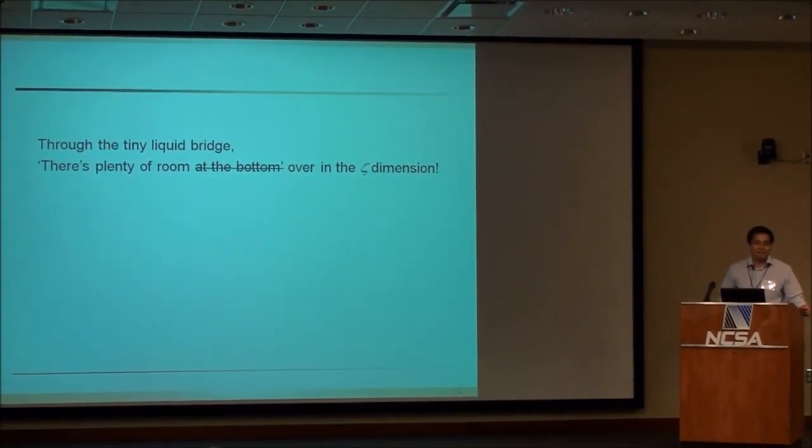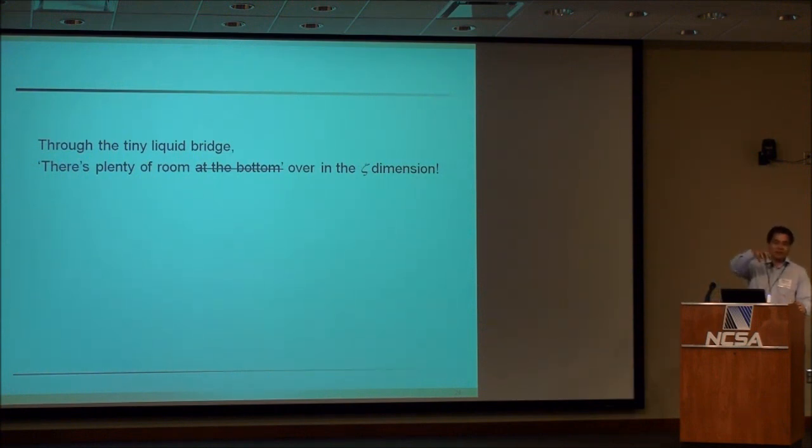Haven't you faced any clogging problems at the nozzle tip? Doesn't the metal clog? No. The key issue is how you find your optimal speed for pull-up, so you have to find that speed beforehand. Once you find it, say from 500 nanometers per second to 700 nanometers per second, within this range your wire growth will never be faster than your pull-out speed. The only clogging issue will come up if you're pulling up too slow. If you pull up too slow, the wire grows into the nozzle. Otherwise, it's purely based on electrolyte liquid, so there's no clogging issue.